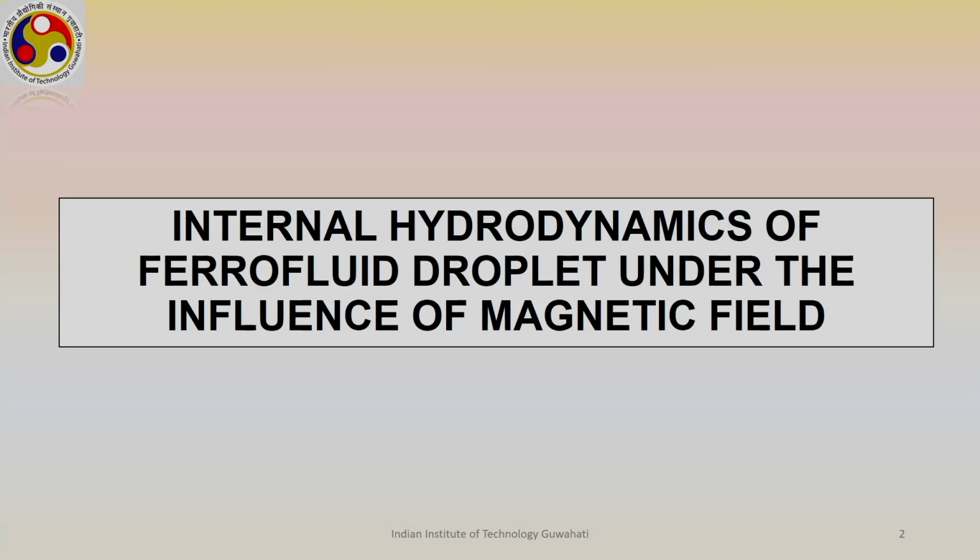Good afternoon. We will continue our discussion on the micro PIV measurement, and today we will see that using micro PIV analysis we can measure the microscale flow features both qualitatively as well as quantitatively. So, to discuss that aspect, I will be focusing today on the internal flow dynamics of a ferrofluid droplet under the influence of a magnetic field.